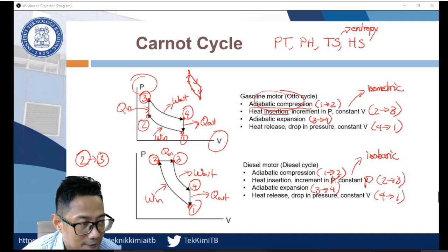Normally, when you check the engine based on Otto cycle, the top speed is relatively much higher compared with a diesel engine. On the other hand, the advantage of a diesel engine is that it should have higher torque. So heavy duty vehicles like trucks and buses should be based on a diesel engine.